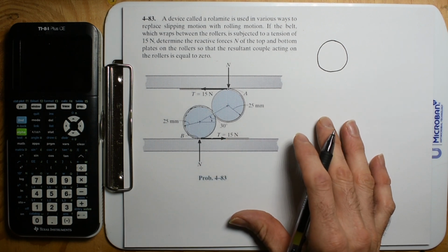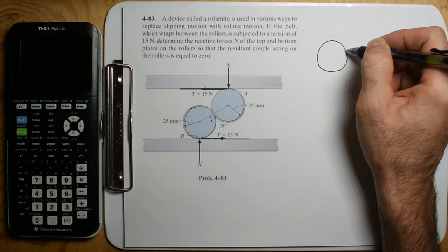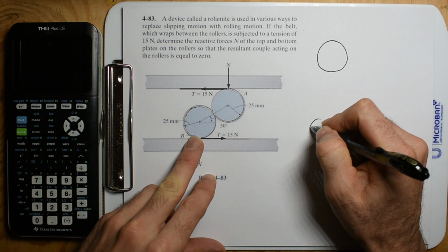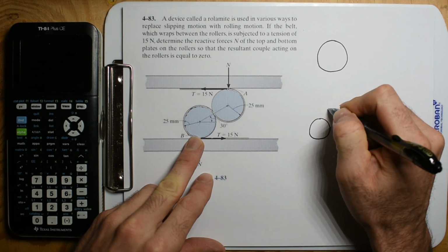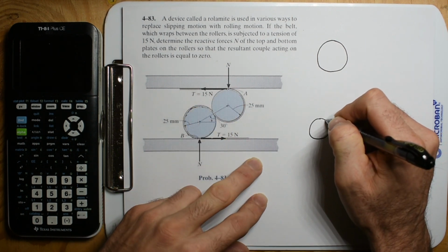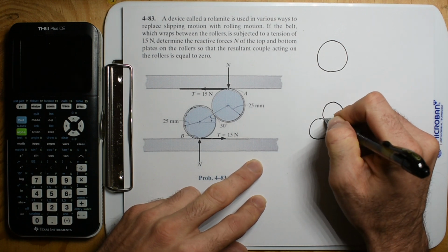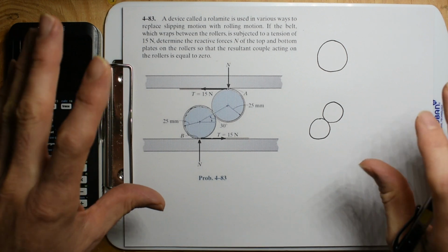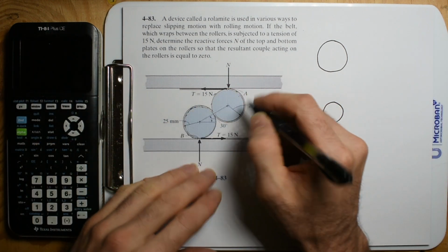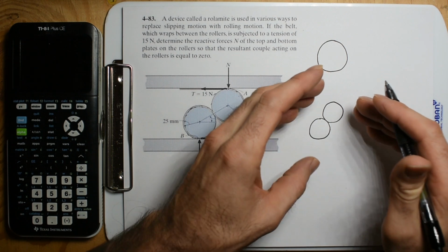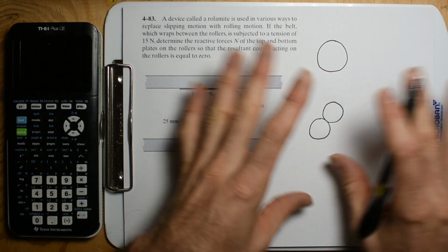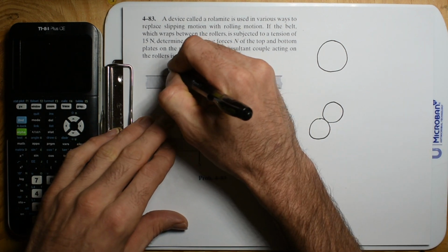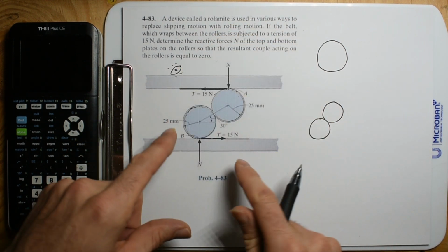It's one of those where you actually don't want to just chop out an individual disc. So let's do it like it should be done, where you want to chop out the whole thing, everything in blue. So we're going to take both those rollers, and then we're just going to apply forces. How I like to do free body diagrams is, anytime I'm going to chop out something, I pretend like it's in outer space, just floating there with no forces. You don't have any gravitational forces around. And then I go back to Earth, and then see what forces are known.